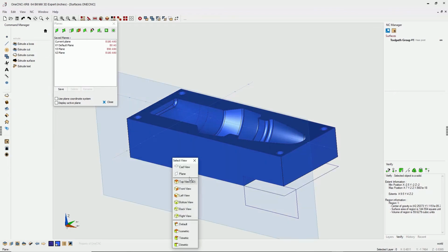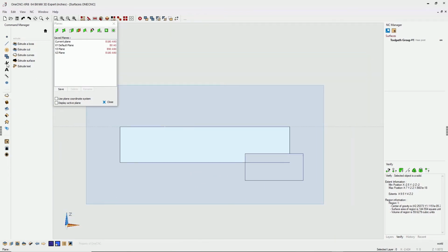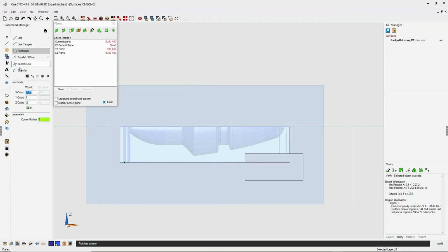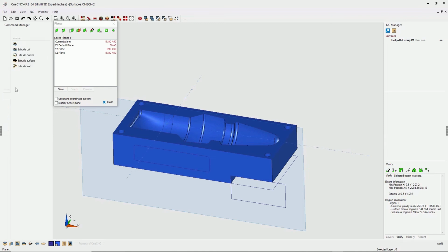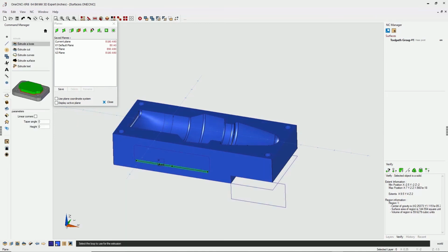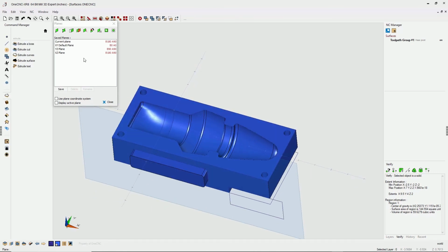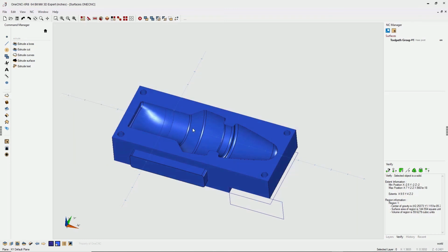Alright, let's keep on going here. Let's create another shape. Just to speed things up, I'll make another rectangle, but this time let's give it a corner radius also of 1/8 of an inch, and I'll just drag out a shape, something like that. And instead of extrude cut, why don't we use extrude boss? I'm just going to pull that out. Now, of course, you can type in dimensions. I'm just dragging with the cursor just to speed things up.